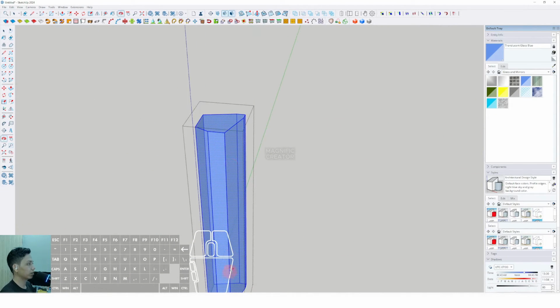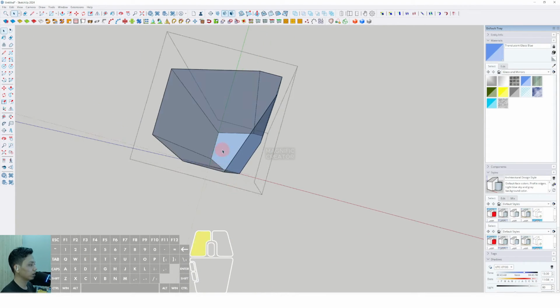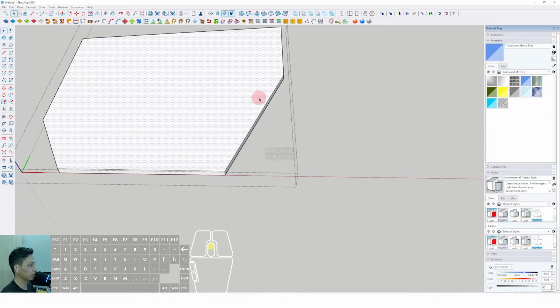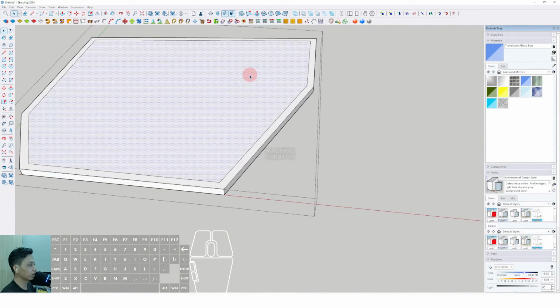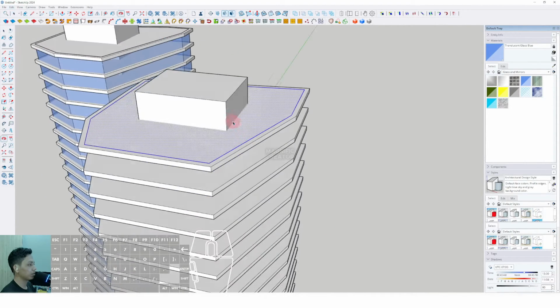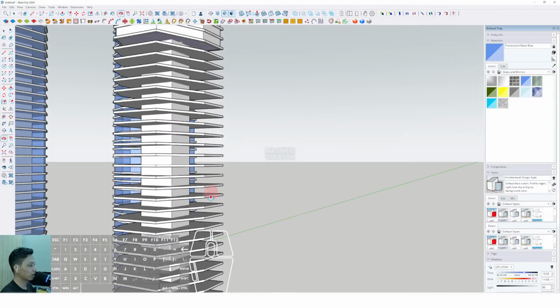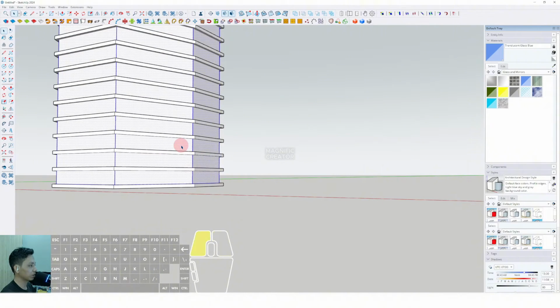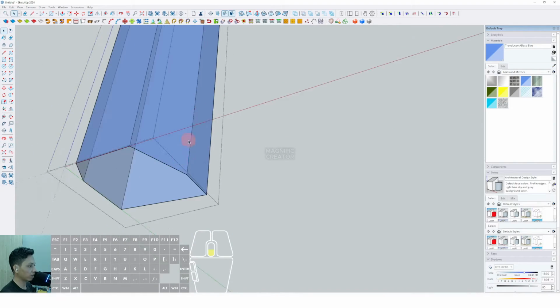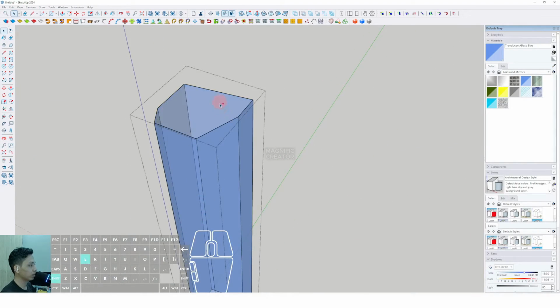Okay, then we can activate the highrise model. We can delete the top and bottom surface over there. Then we can triple click again, offset it inside around 1 meter. Then enter. Then we can click the surface, copy, exit from the group, paste in place, and push it till the ground floor. Triple click, make group, assign the materials, and delete some unnecessary plane in here.